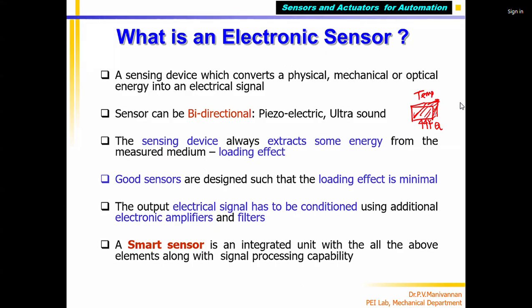Now I want to measure the temperature of this metal cube. What I will do is use a thermocouple. The thermocouple junction will be made to touch the surface. If it touches, what will happen? The heat will be transferred from the surface. Suppose the temperature at this location is 50 degrees. The metal cube, a solid cube, is heated by supplying heat energy, and currently a temperature of 50 degrees is maintained. Now I want to measure the temperature with the thermocouple. Before touching, the thermocouple junction is at room temperature, for example 30 degrees.